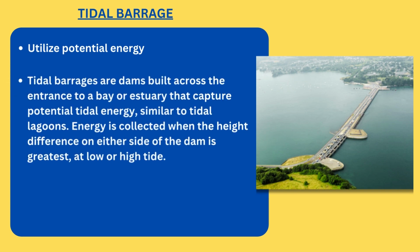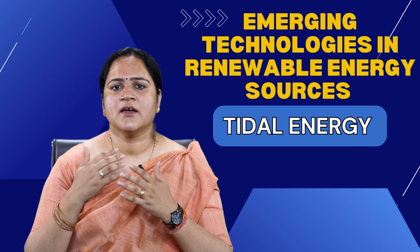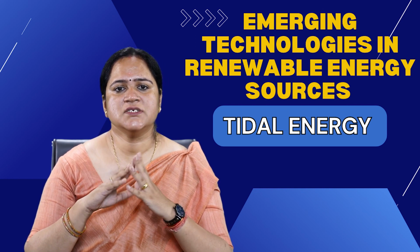The tidal barrage generally utilizes potential energy. How and why? These tidal barrages are generally dams built across the entrance to a bay or estuary that capture potential tidal energy, similar to tidal lagoons. Energy is collected when the height difference on either side of the dam is greatest at low or high tide. So, we are generating energy through the difference in heights, basically utilizing potential energy.